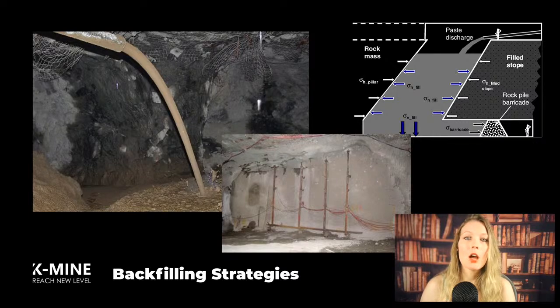Backfilling strategies also play a critical role in optimizing stope layouts. Hydraulic backfill and paste backfill methods are commonly used to provide structural support while allowing for adjacent stopes to be mined safely. Studies on backfill mechanics show that the consolidation rate and cohesion properties of backfill material directly affect stope stability. Incorporating backfill parameters into stope design calculations can enable larger stopes to be extracted without increasing the risk of wall failure.